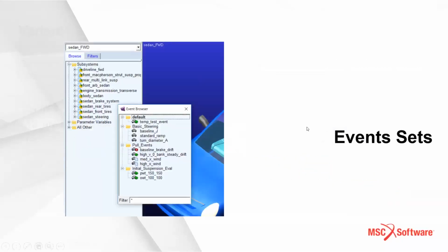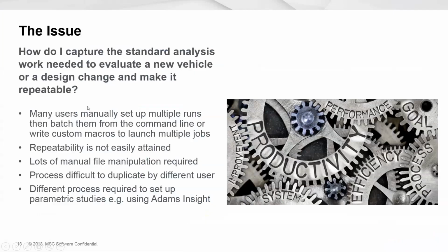So let's talk about event sets, which is where I thought I was going, but now we're there. So the issue that inspired us to create event sets was the question of how do I capture the standard analysis work that's needed to evaluate a new vehicle or design change and make it repeatable. Many users manually set up multiple runs and then run them in batch using a command line script or custom macros which launch multiple jobs.